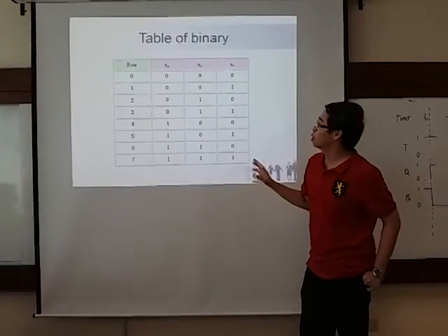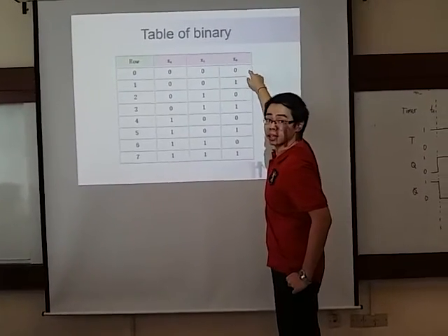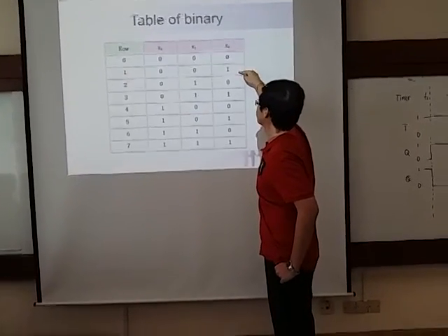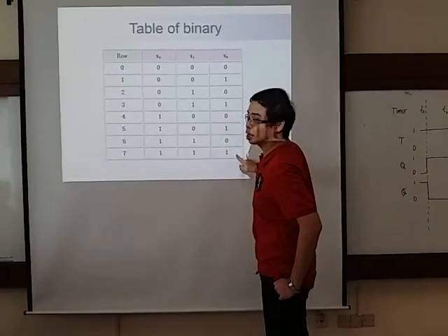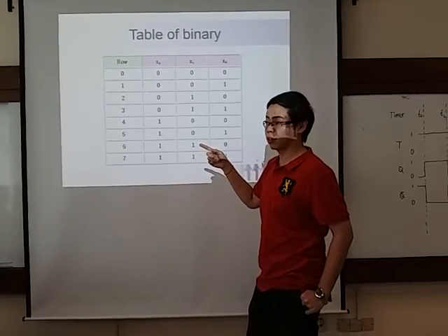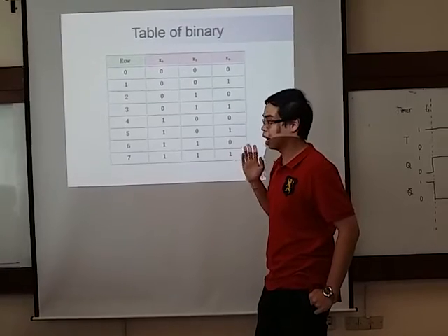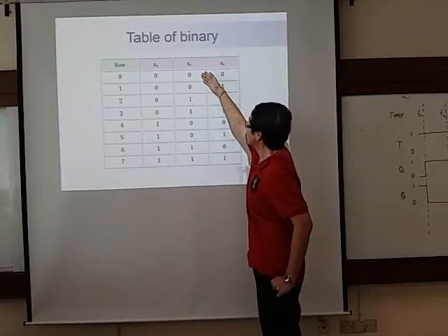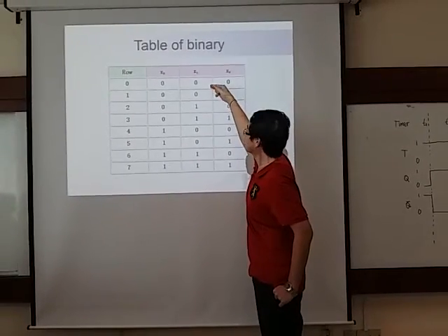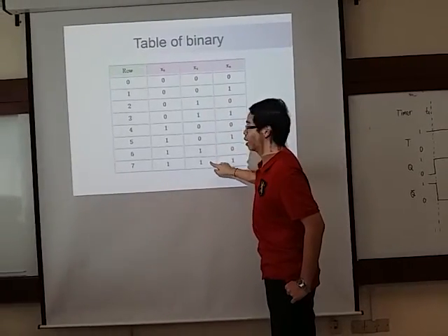The important thing in this table is you can see the period and the frequency. X0 is always changing from 0 to 1, 1 to 0: 01, 01, 01, always changing. But in X1, if you remember the frequency divider theory, the frequency becomes 2 times slower, right? So X1 toggles only every 2 rows. That means at 2, it toggles back: 0011, 0011, like that.